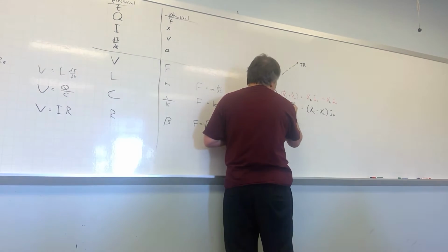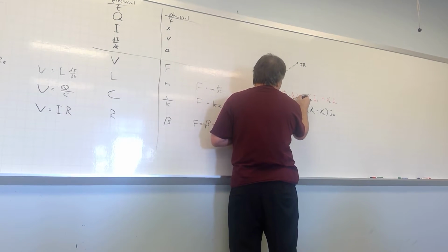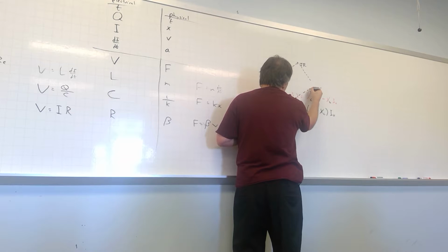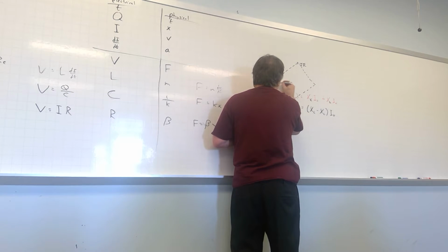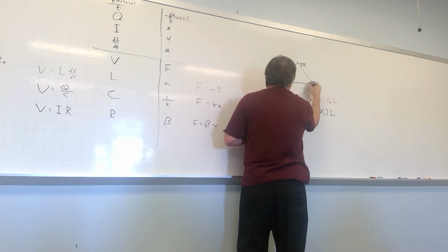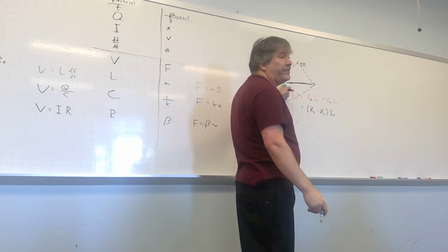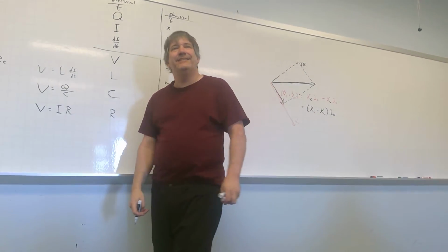And what do I get when I add those two vectors? I mean, vectors in the complex plane, a real part and an imaginary part, act exactly the same way as two-dimensional vectors on an XY plane. I add those two complex numbers, I get this one. This is my overall voltage phasor for the three elements combined.